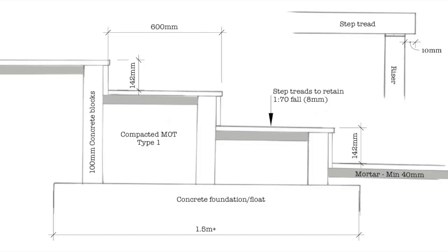But back to what I specify 9 times out of 10. As basic structures go, I'd normally suggest a concrete block or brick structure laid on a concrete footing of some sort depending on the existing land. This tends to do the job, and then you can backfill behind the structure and clad both the riser and the tread, or if you build the riser out of brick it might not need cladding depending on the aesthetic finish you want to achieve.